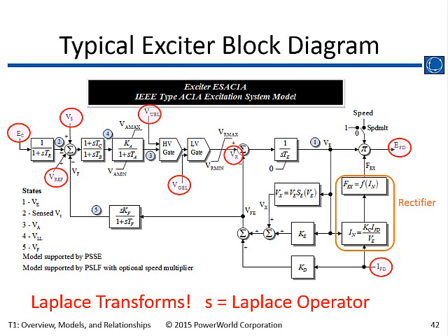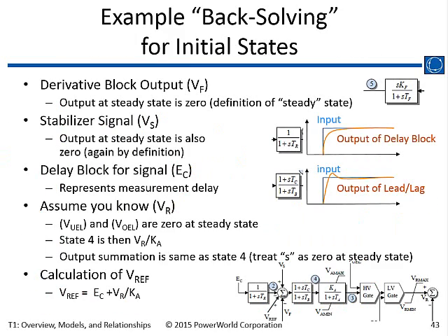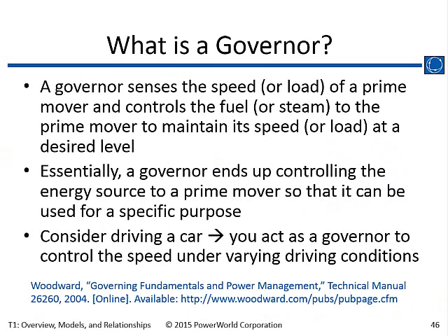And we give you a couple options in PowerWorld, which we'll talk about. A simple option is to say, hey, if this is 11 and that limit is 10, just change that limit from 10 to 11. And it solves the problem, but the question is, is that legit? Maybe it is, maybe it isn't. So the details do matter in the response that you get.